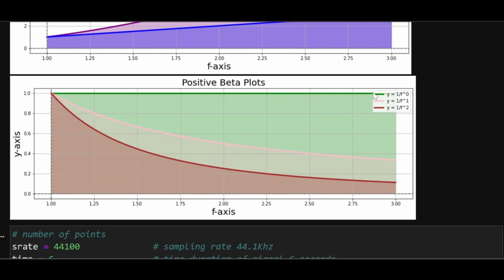This is the classic definition of white noise, which essentially means that the power of the noise is equally distributed across its spectrum. The frequency has no bearing on the power, because power is equally distributed at all frequency components. It has no selective preference for any particular frequency, and that's the reason why it's called white. It is a combination of all the frequencies, a combination of all the possible colors. And in time domain, it actually is an impulse function, a function which starts at 0 and goes up to infinity. That's how white noise gets generated. It's a very important concept.